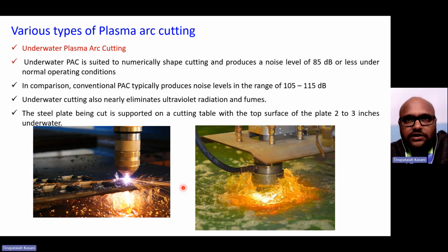The third one is electric discharge machining, where a spark is generated between the tool and the workpiece. The spark results in a high amount of heat energy, causing melting and evaporation, followed by cavitation due to the formation of bubbles. The next one, electrochemical machining, removes material from the workpiece due to the chemical action of the electrolyte. Before the material gets deposited on the other electrode, the tool, the electrolyte flow removes the material from the machining zone.